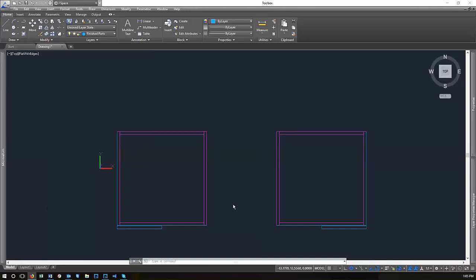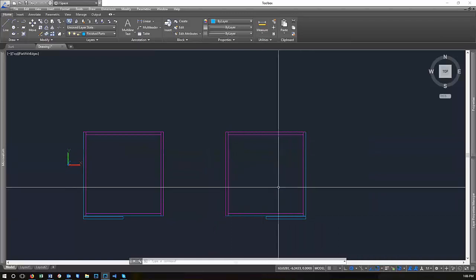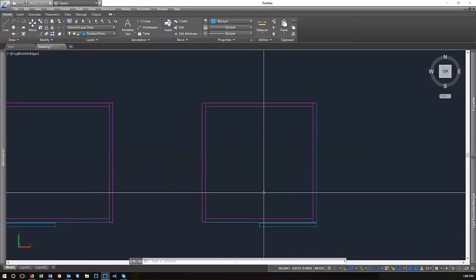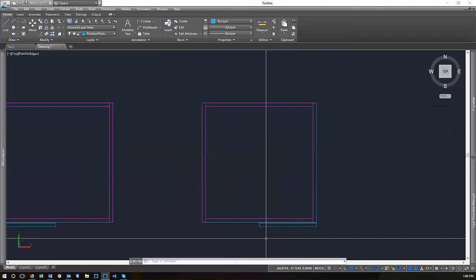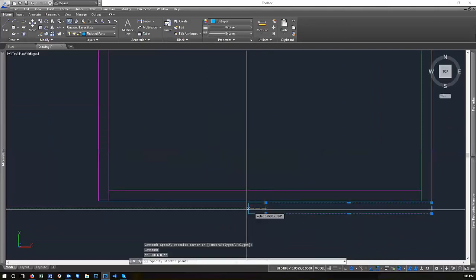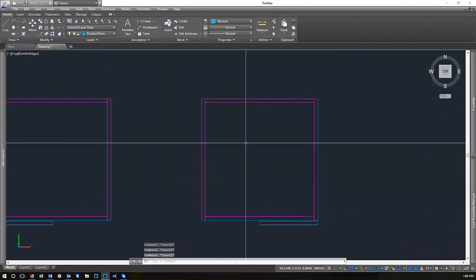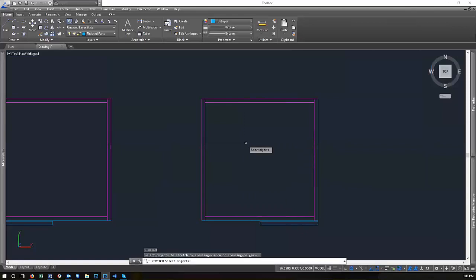All right. Our next one is stretch. Very helpful. Continue using the same example, but say field dimensions have changed for this drawing, and so you want to change this. You want to either make the door bigger or smaller. It's very similar to the command we use to stretch these parts out. It's stretching these two grip points, so you want to keep in mind what you're actually stretching. Stretch can be used as a move command, as well as similar to an extend command. It will lengthen lines. So I'm going to hit S, and that will bring up the stretch command.